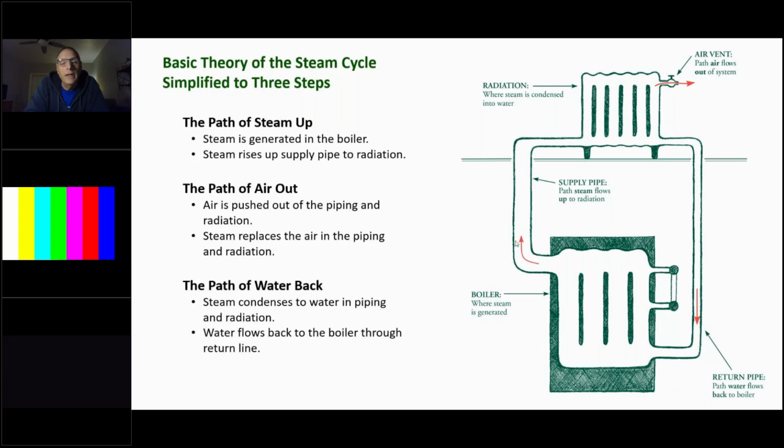But if you've got oil in there, it will produce a skim on top of that water, and it'll be like steam bubbles popping up out of that water. And that's what causes that water line to bounce. And again, if it's bouncing like that in the gauge glass, it is just rocking and rolling in that boiler. And we've got to clean that boiler.